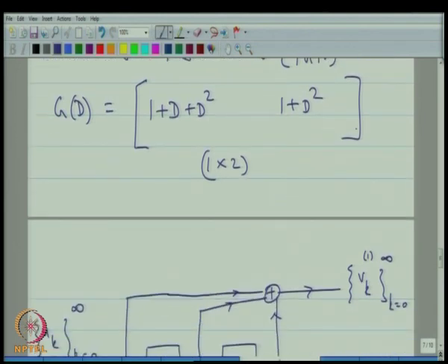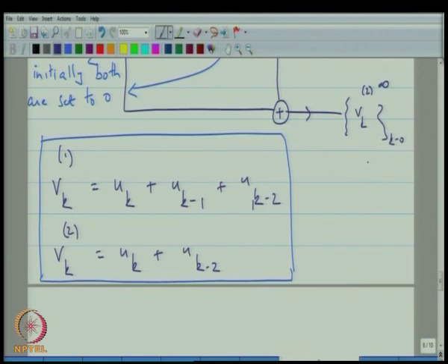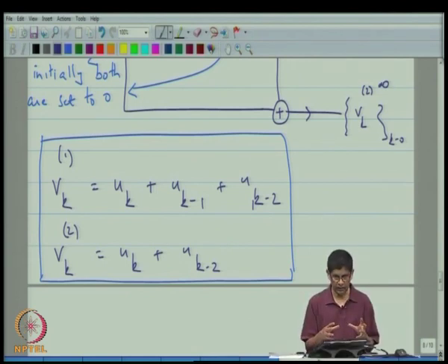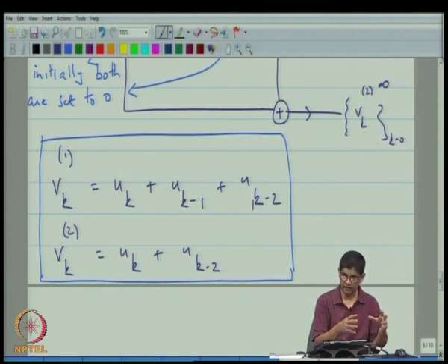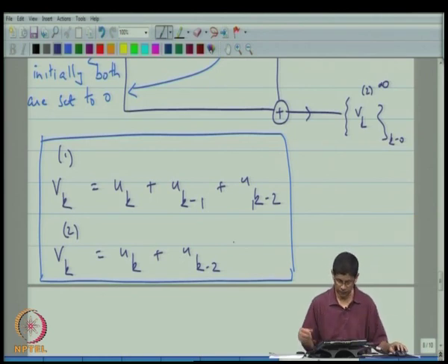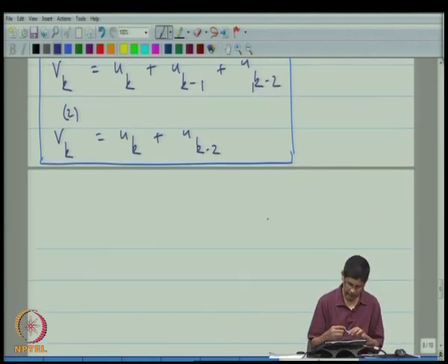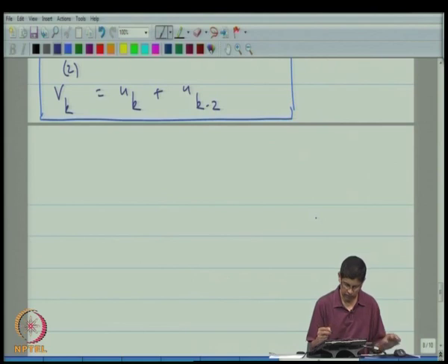So how do we actually arrive at that, and what does it mean exactly? To see that, you'll have to look closely at these equations, and if you look at it closely enough, it looks like you're actually convolving the input with a certain sequence of finite length, and that is what is giving you the output. And as you know, if you have a convolution in the time domain, you can represent it as a multiplication in the transform domain, right? Like for example with Z transforms, and your D is playing the role that Z plays in the Z transform.